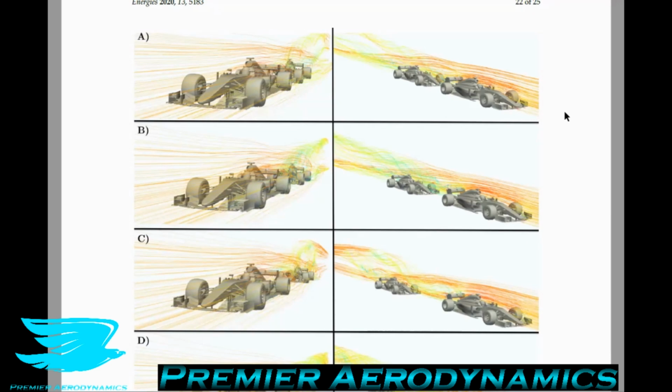And that means that not only do we have this chaotic, ugly flow, but also the streamlines are at an angle up, which means that some of the flow control devices are not really seeing a very high angle of attack. The effective angle of attack is lower now because the streamlines are at an angle up. So for example, you might expect the rear wing to have overall an angle of attack of 30 degrees, because each element has its own angle of attack. Let's just say, to simplify it, the entire wing has a 30-degree angle of attack.